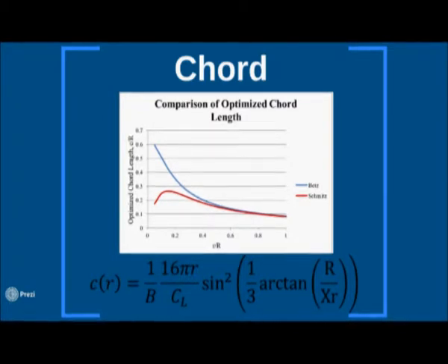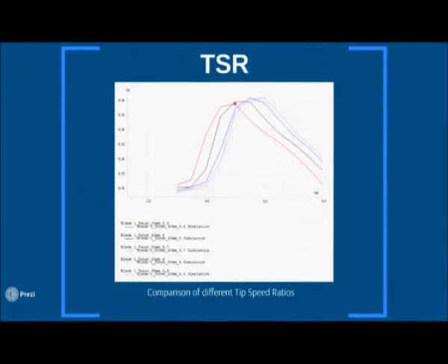After having calculated the chord lengths, manual adjustments were made near the hub to create the least amount of drag with the best structural stability. TSR was initially estimated to be 4.2 based on existing literature for small turbines. The chord lengths were then calculated at each interval using Schmitz's equation and entered into Q-blade together with the twist and airfoil types. We then ran simulations on Q-blade to obtain the CP and estimated power output for each case.